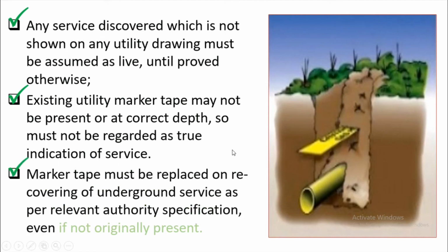Marker tape must be replaced on recovering of underground service as per relevant authority specification, even if not originally present.